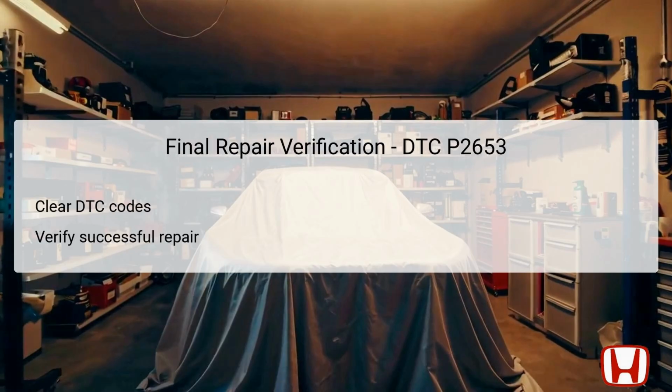Upon completing all necessary repairs related to DTC P2653, it is critical to clear the DTC codes. This is achieved using the Honda Diagnostic System, HDS. After clearing, the vehicle should be monitored for any reoccurrences of the DTC or related symptoms.